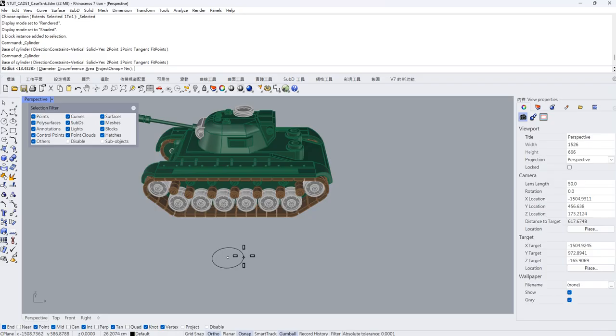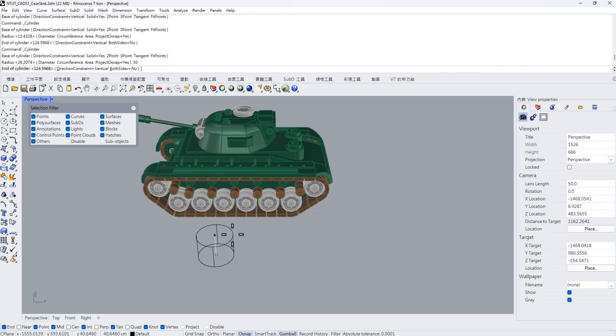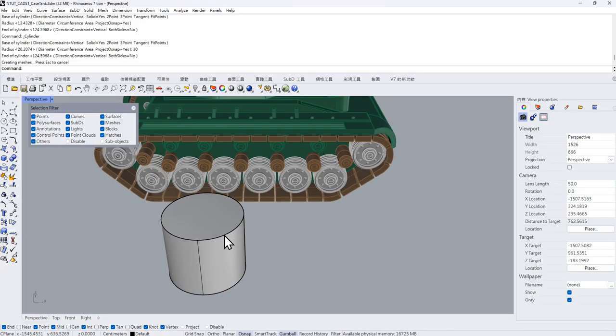Remember, please hold on your shift key so that you can make this face the X and Y direction. Let's do it again. Choose center, and you can define a radius. For me, I want to use 30. Enter. Extrude probably around 60 or 90 is too much. Probably around 50 will be quite enough. Okay, so now we have this cylinder.